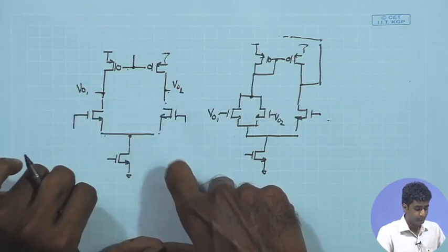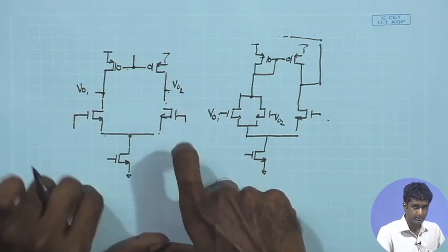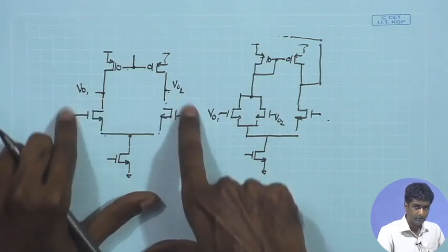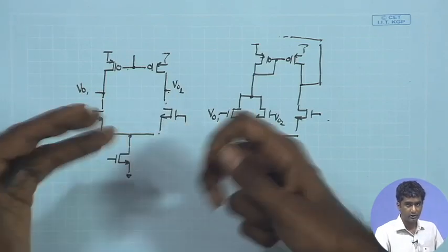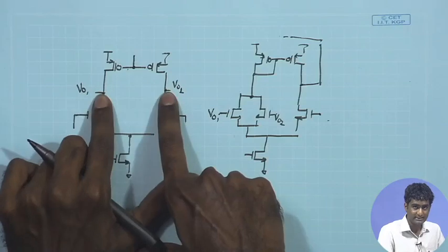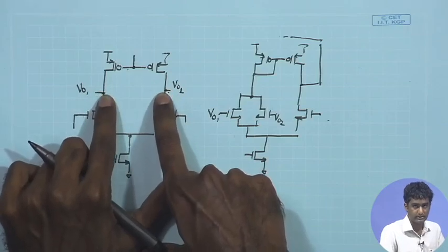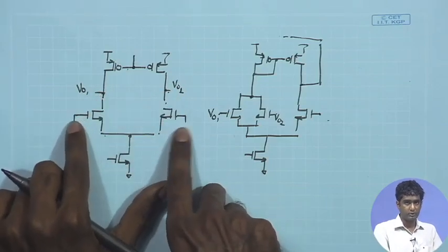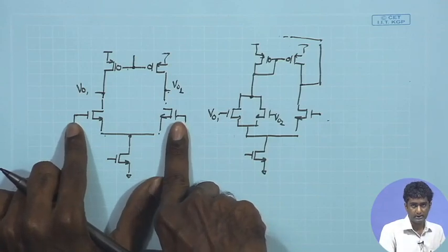While opening the loop, we can also do the same analysis. We can also keep the same RF, because as long as we are ensuring that the VO1, VO2 DC points in the open loop conditions are going to remain the same, that will also ensure that the input DC points over here are also the same.